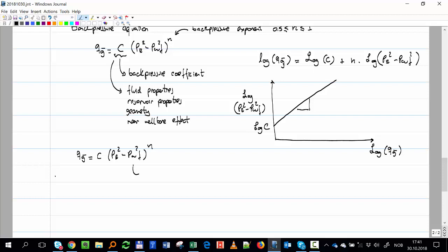you know that PWF has to be equal to or lower than reservoir pressure, right? Because it cannot be higher. Otherwise, you will be injecting. So you know the physical range, and you know you won't have any problems. So you can try just different pressures below that.